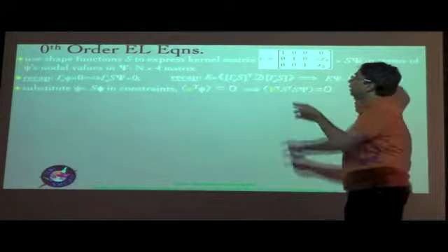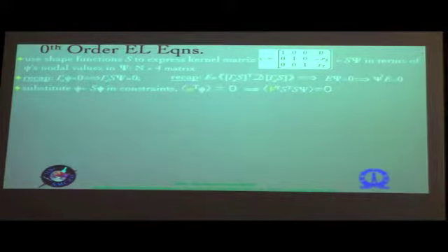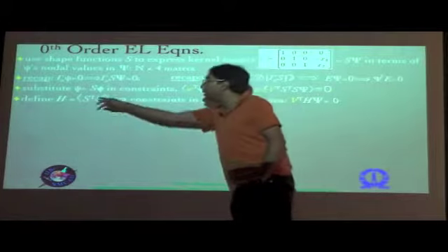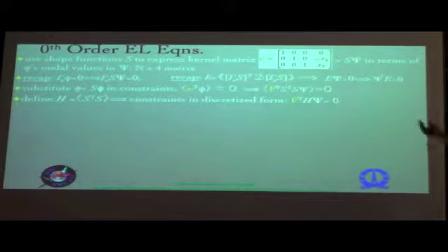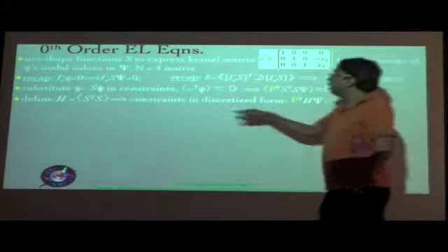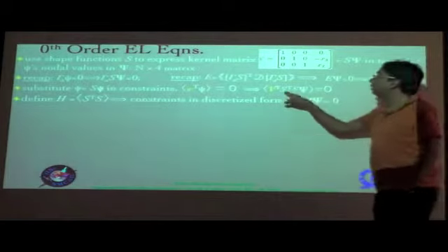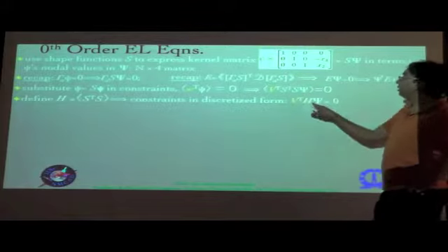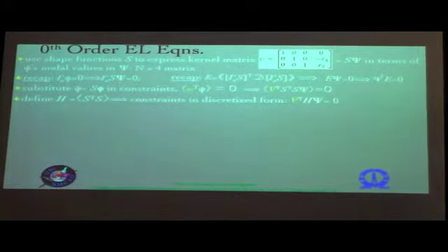And you just have an integral of S transpose S, for which we will give a new notation. We'll call that H. So H is defined as the area integral of the shape function transpose multiplied by the shape function itself. Right? This implies that the constraints in the discretized form can be written in a much simpler fashion as just V transpose times the integral of this, which is H, times capital Xi equal to 0. So this is what we will use as the constraints hereafter.